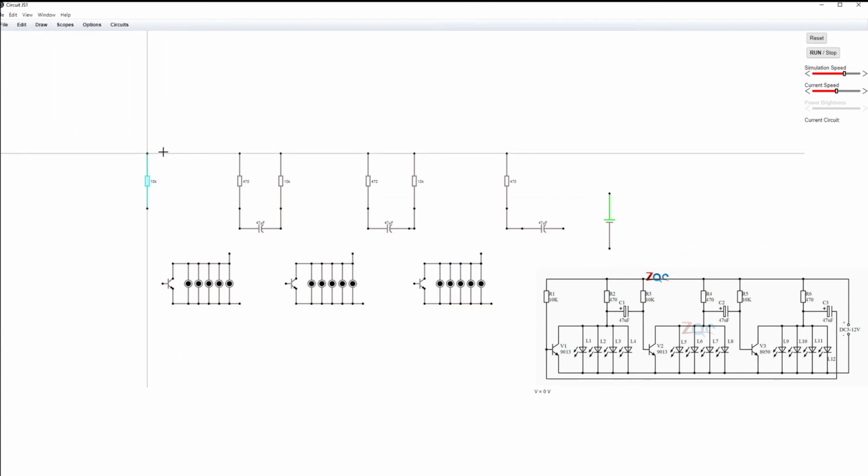So now let's just finish off this circuit. We have all these lines at the top. They need to be connected together. And we need these wires at the bottom to be connected together. So all our transistors and our LED lights are connected to ground. This 10K resistor over here connects to that transistor.